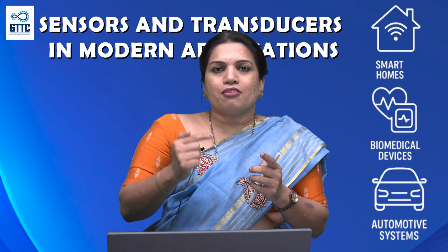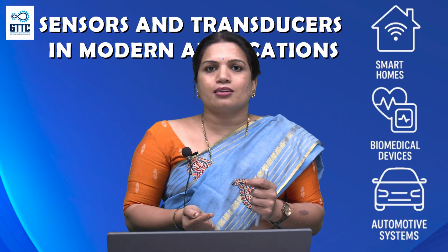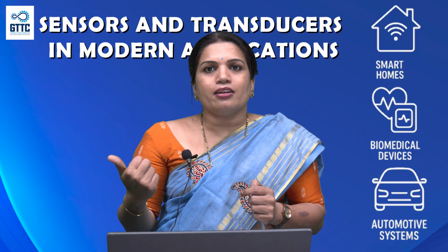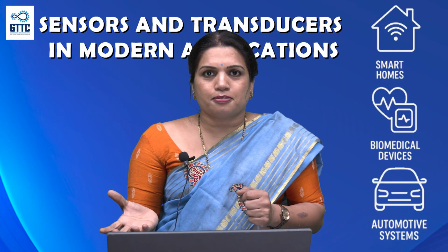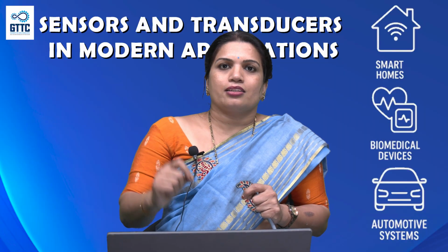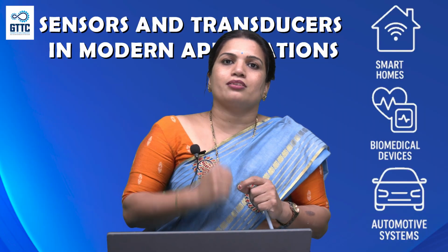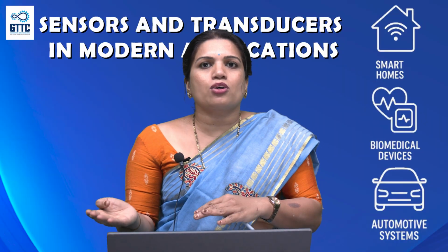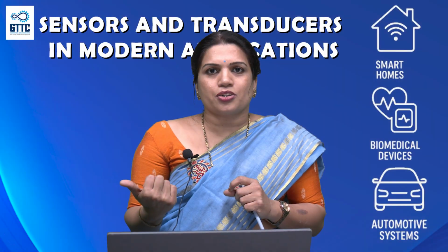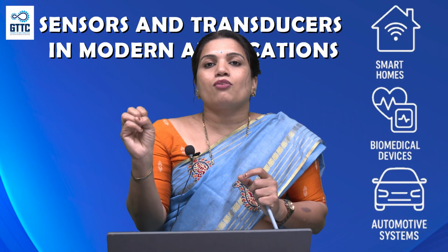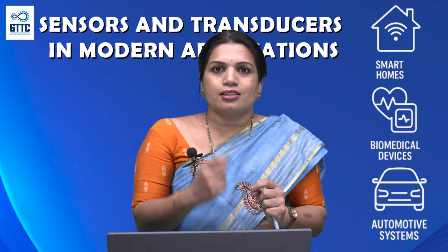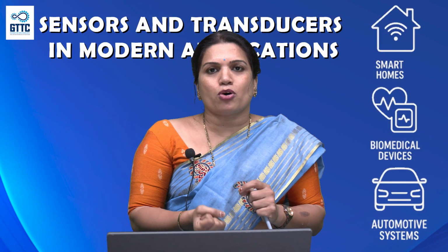The processor, on getting a level lower than the threshold, gives a signal to the actuator. The actuator automatically sprinkles the water. If the same sensor senses soil moisture above the threshold, that signal also goes to the processor, which gives a signal 0 to the actuator, that means the water pump. Here the actuator is a water pump, and the sensor is a soil moisture sensor.